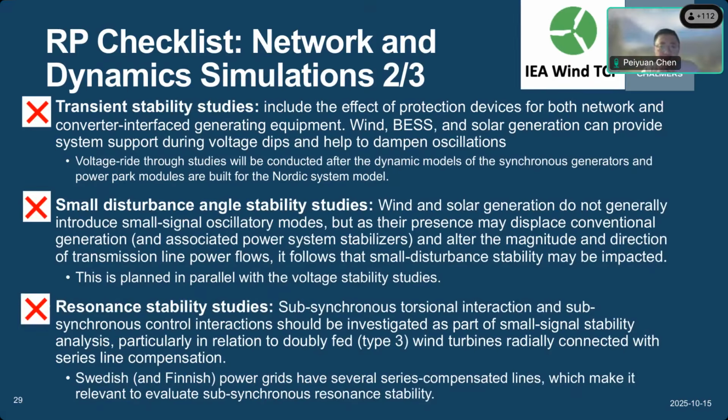I think the trend from the transient stability point of view, which is also very coupled to these aspects, is that we would like to see the different control modes of the wind and the solar in the system to support the grid, the rated power and the voltage. And also there will be new requirements coming out on the demand on the reactive current injection during fault. So this is something we will definitely start with.